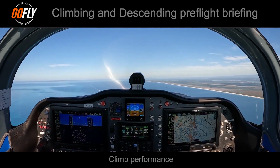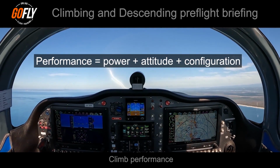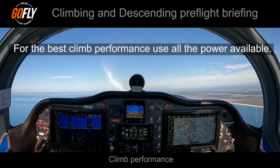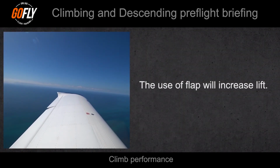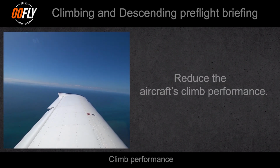We know that the aircraft performance is a factor of power plus attitude plus aircraft configuration. For the best climb performance, we should be using all the power we have available. The use of flap will increase the lift available, but also increase the induced and parasite drag, and this will reduce the aircraft's climb performance.